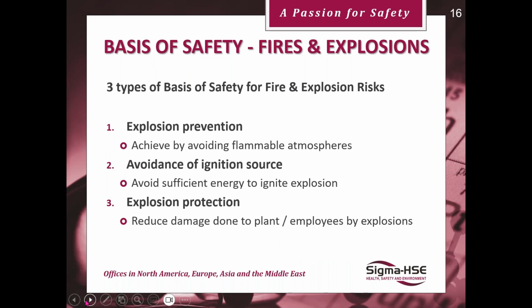Explosion protection will not stop the explosion. What it will do is reduce the damage done to plant and protect employees from the explosions. So this is one a lot of people use, even in the food industry. And any of these could be combined. You might think to yourself, 90% of the time I can get away with avoidance of ignition sources, but I'm still going to fit explosion protection for the other 10%.